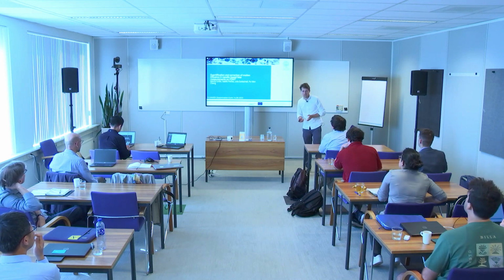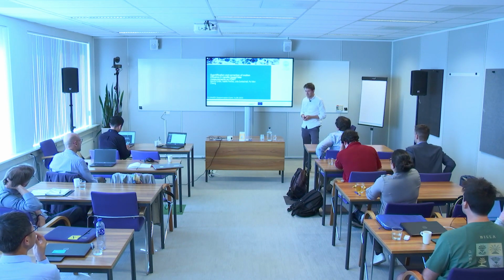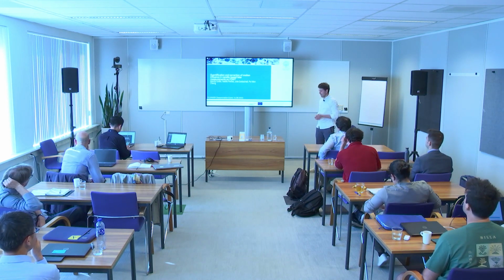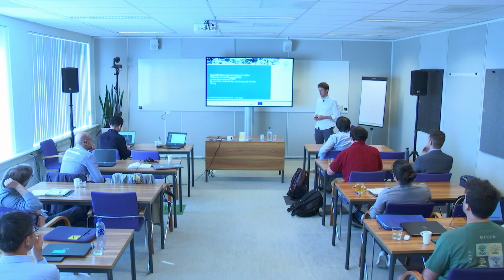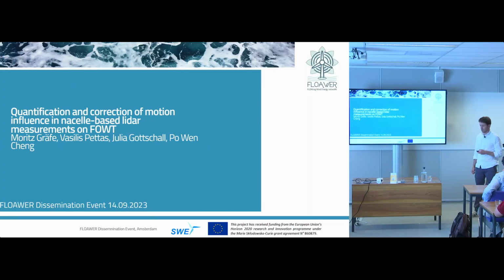Now we have a fairly big jump from hydrodynamics going to lidar measurements. My work in general is on using nacelle-based lidar measurements on floating wind turbines for different applications. Mainly, I am working now on using this lidar inflow information for monitoring applications, so load monitoring.